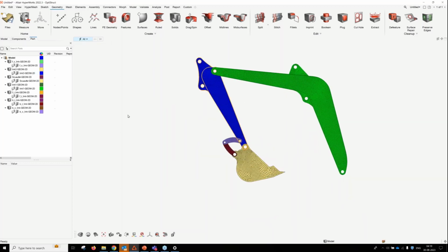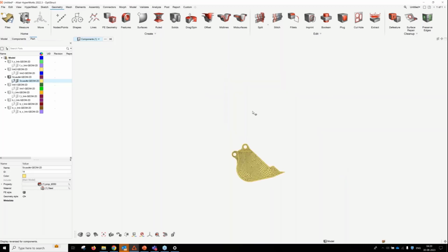Okay, so if you wanted to hide anything, you can just select that component, and you can use the shortcuts either with the right click, or you can just press H. The moment you press H, that particular component is going to hide. And if you want to isolate it, or reverse it, just press R on your keyboard, which is reversing. So this is majorly on the selection front or on the masking front.